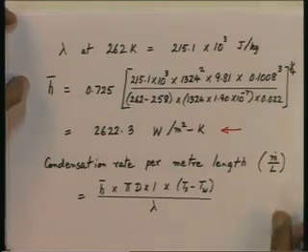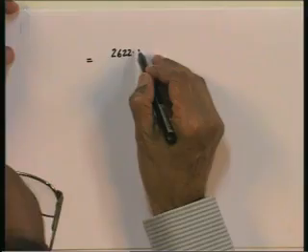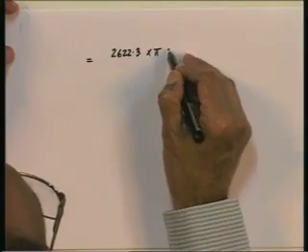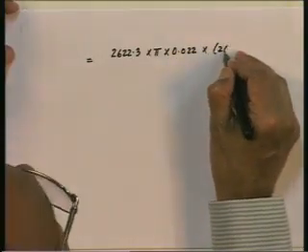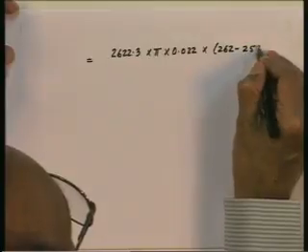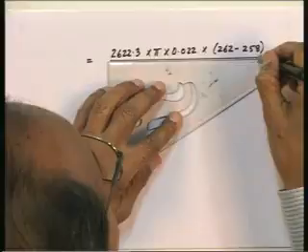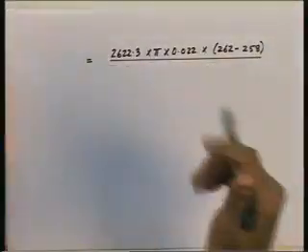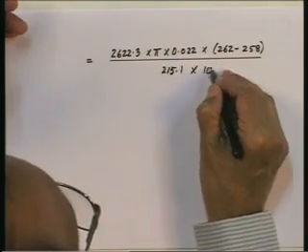So, now again substitute the numbers here. If you substitute the numbers, m dot by L is equal to 2622.3 multiplied by pi, 0.022, into 262 minus 258, that is the delta T, divided by lambda, which is 215.1 into 10 to the power of 3.